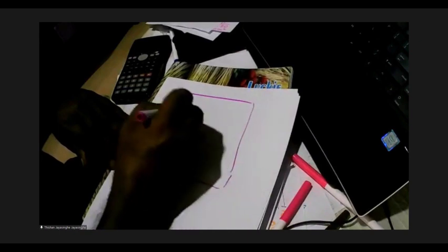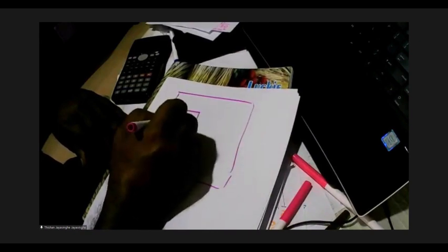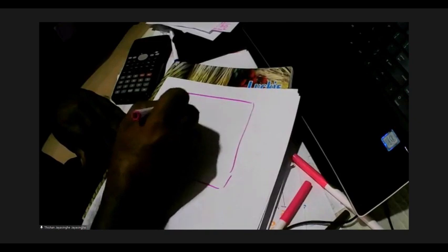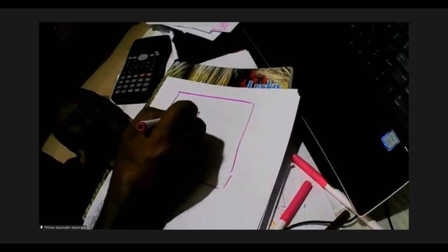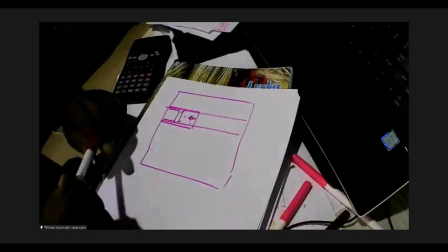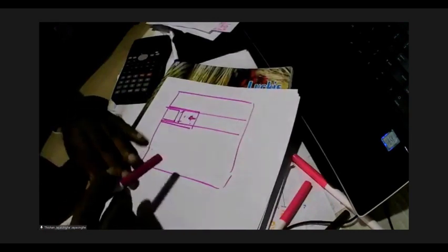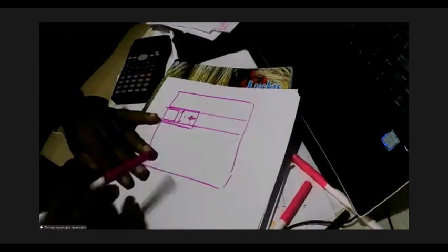So in that case, if you have a slab, a washroom that you wish to lower the slab, we generally keep the dropped area to be around 1.5 meters, 1.4 meters, so that on either side we can run the pre-stressing tendons. So we have to plan these drop areas carefully.